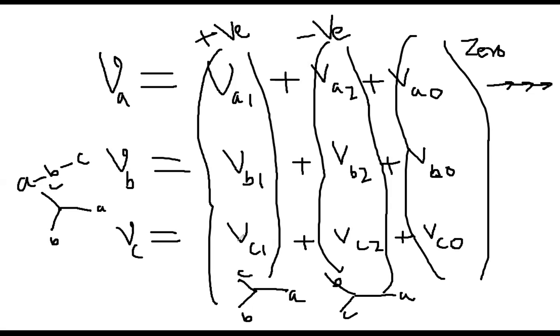This is a balanced system now, but its phase sequence is exactly the same as the original unbalanced system. This is the second set. It is called the negative sequence because its phase sequence is ACB, not ABC. This is the third set. Therefore, what I want to tell you is that this was a three-phase unbalanced system, and I got three new balanced systems. This is one set, this is another set, although they have different phase sequences. But what is the significance of the negative and the zero? You see, these two look like additional components.